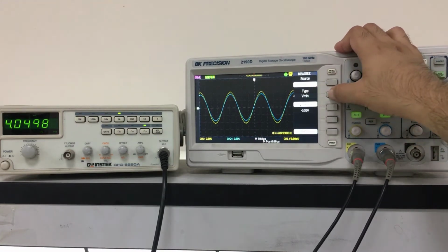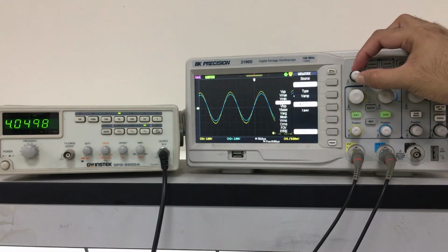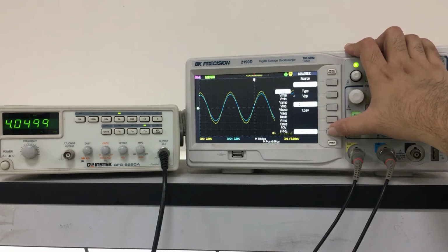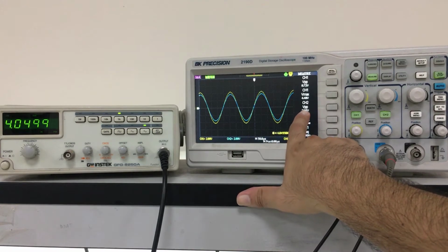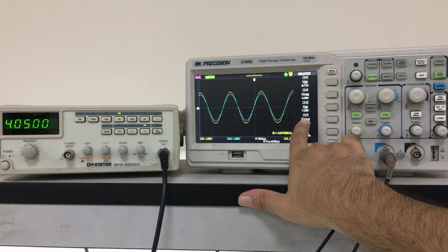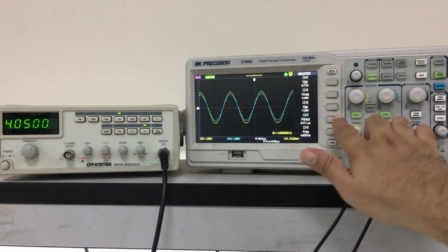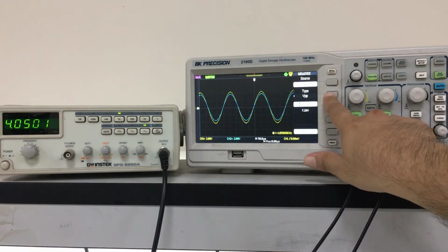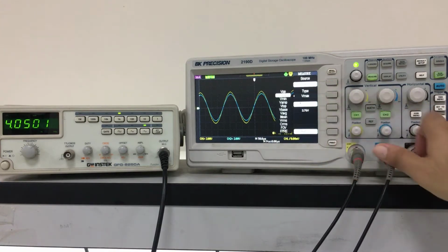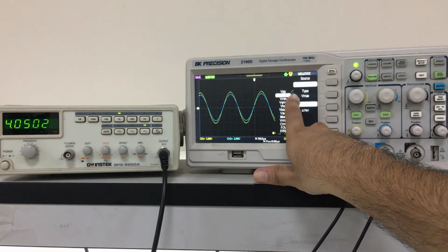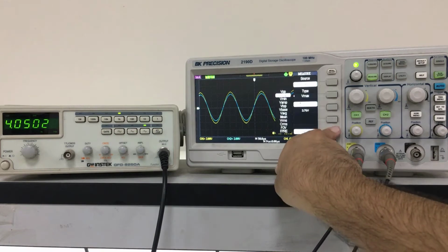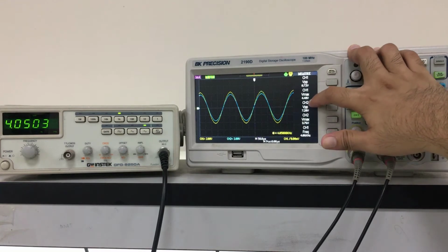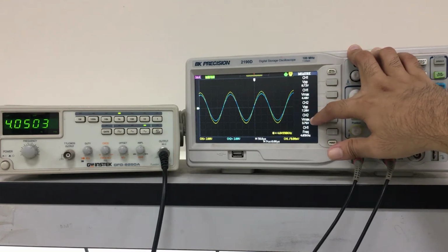I press the corresponding button to get this menu. I rotate this universal knob to get V peak to peak. Then I press return. So now channel 2 V peak to peak is being displayed here. Now I will change this to channel 2 Vmax. I do that by pressing this button. Category is again voltage, channel 2. Type will be Vmax. So I press this once and see that Vmax is already selected, so I don't need to manipulate anymore. So I press return and see that channel 1 V peak to peak, channel 1 Vmax, channel 2 V peak to peak, and channel 2 Vmax is displayed here.